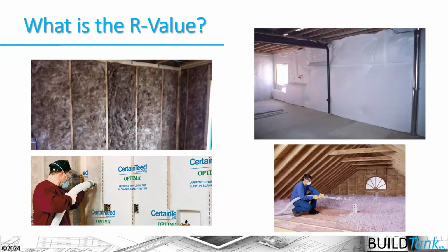Therefore, the installer should be verifying and doing some level of quality assurance to verify what the R value of that material is, and leave a certificate that can be inspected at the time of install, so that when we go out there after install, we can determine whether they achieved the R value that's required in that particular assembly.